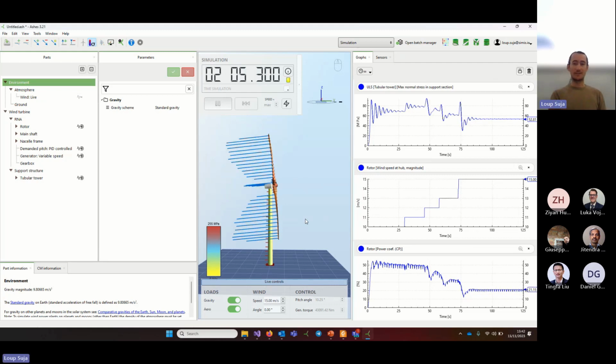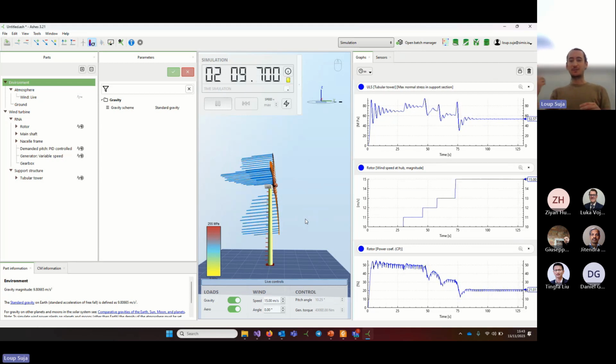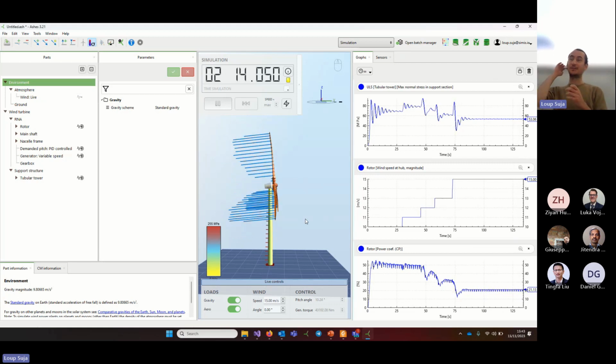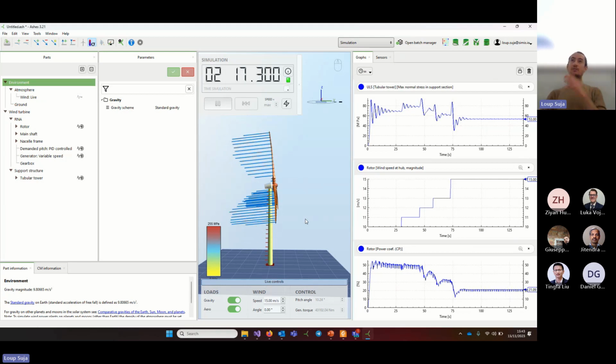And it's very important when you're designing your controller, the system that is going to decide how fast the rotor is rotating and how to pitch the blades. It's very important that you make sure that the frequency of this tower shadow, called the blade passing frequency, doesn't match the eigenfrequency of your support structure, because otherwise you could get resonant effects.